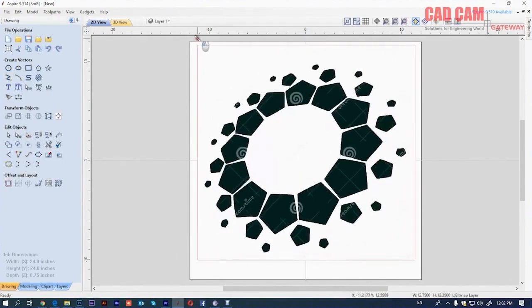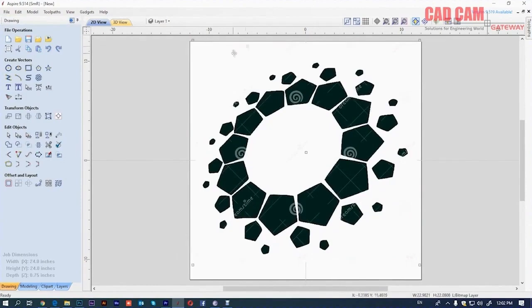Scale it. Enlarge it to the size you want it to be. It's generally better to maximize the size for better accuracy. But keep in mind for bitmap tracing that the quality of your bitmap image should be relatively good. Try to have it in separate colors. The colors should be clearly visible here. You can see that there are watermarks on this image.